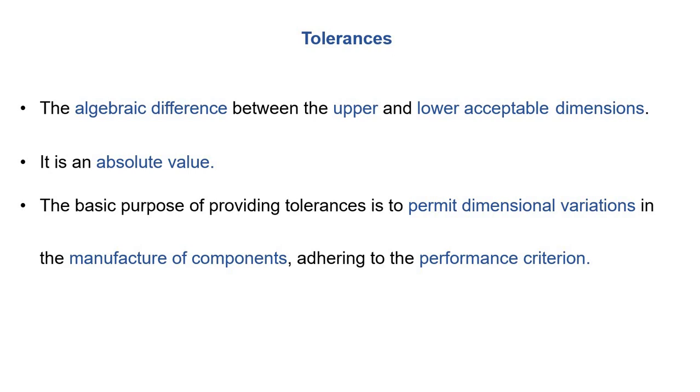These are the allowable limits, which have two sizes. The first is the upper limit and the second is the lower limit. The upper limit indicates the maximum size of the shaft or hole that can be produced for the mating part, while the lower limit indicates the minimum acceptable limit that can be reached by the product so that it will have the desired functionality.